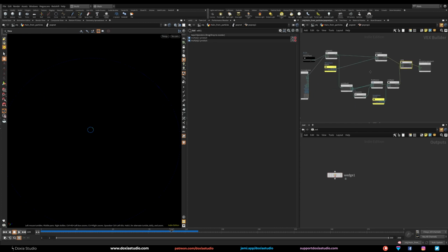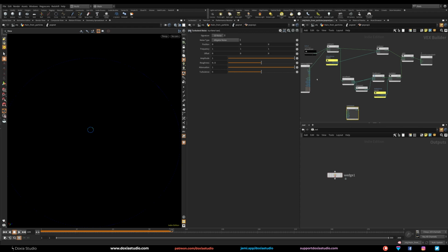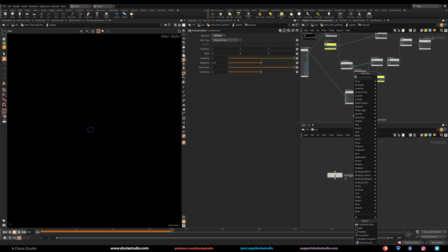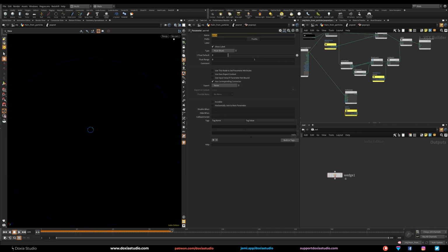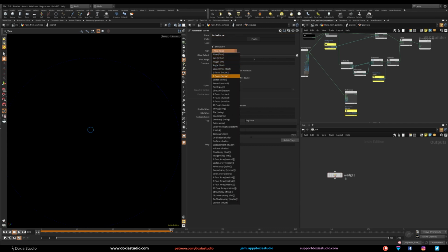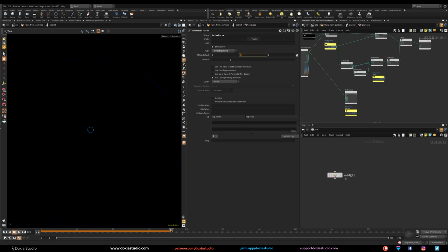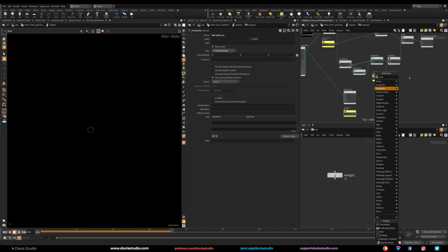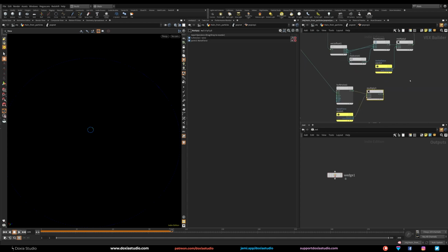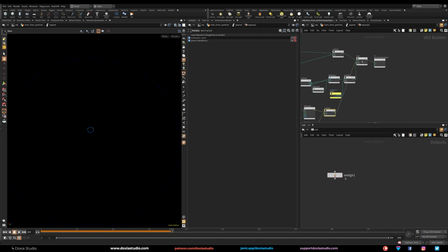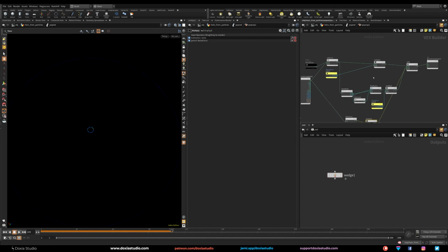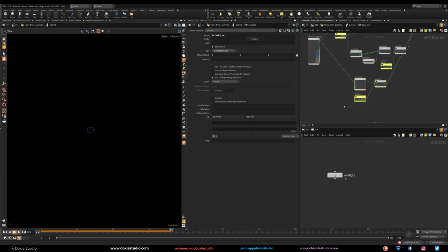Now it's too linear for my taste. You don't need to add this, but I like to add a little bit of turbulence. So let's add turbulence. Let's link the position to our position. Let's come here, 3D noise. Let's add another parameter for our turbulence force. Let's go with noise force. And at this moment, I want it to be a vector, okay, to control the force for every single coordinate. And again, multiply to control the force of this, okay. And let's add this multiply to our add. So right now, our final velocity will be the attraction force, the vortex force, and then our turbulence or noise force, okay, everything combined. And I want to promote these create input parameters.